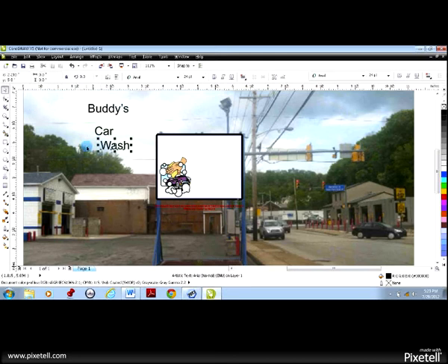Before placing the text on the sign, I would then grab each one and I would pick a font. As you see, when you click on the word, the fonts pop up here in the left-hand top of your toolbox. Always pick a bold font. It works better on a sign. I usually set it in the left-hand corner and drag the right-hand corner for sizing.